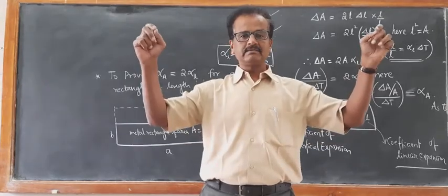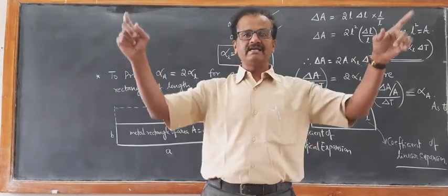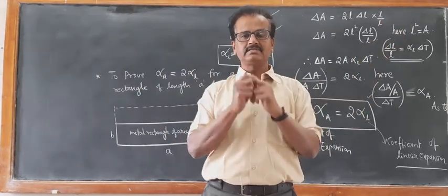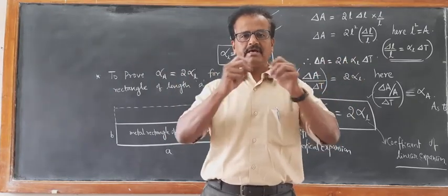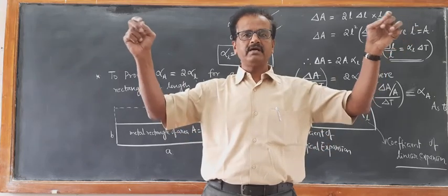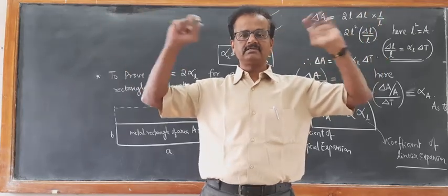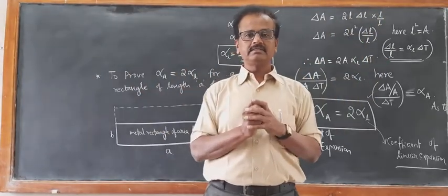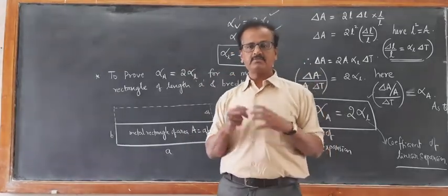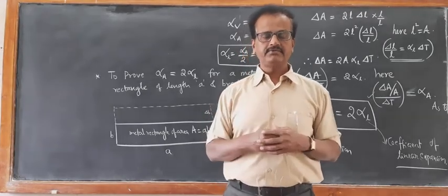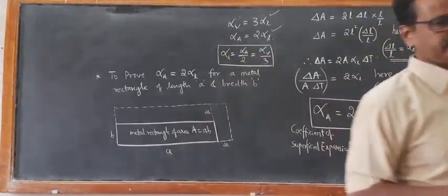And you might have a common observation. The electric lines between the poles will be found sagging, hanging in the summer season because of expansion. Because of hot sunshine, they expand. Therefore, purposely between the two poles, when they are connected, they leave a little extra length so that they can expand, and in the winter season they can contract. So this is the application of thermal expansion that we see in our day-to-day life. Practical application. Okay, let us see one example of thermal stress.